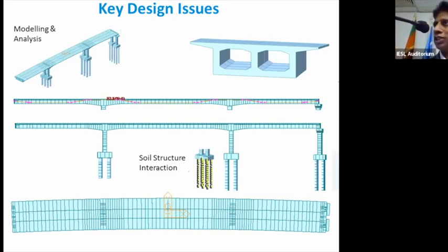One aspect I want to highlight is the soil structure interaction. You talk to the geotechnical engineer, you work out the springs, the bearings, skin friction, and the lateral springs. You add them into the model, and it gives the actual behavior. Also, you need to look at the articulation I mentioned, where the structure should move, and that also needs to be included in this model. Only then does it represent the actual behavior of the structure, what you would expect in a natural way.